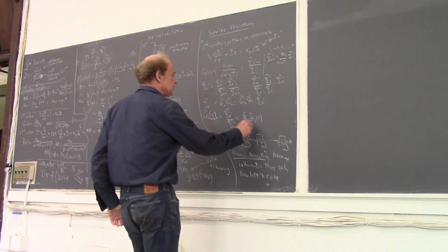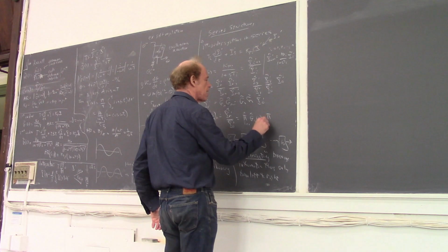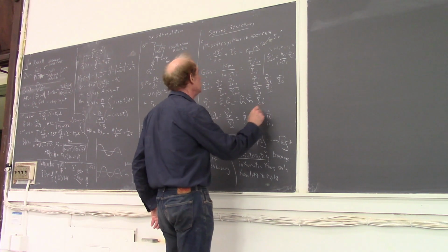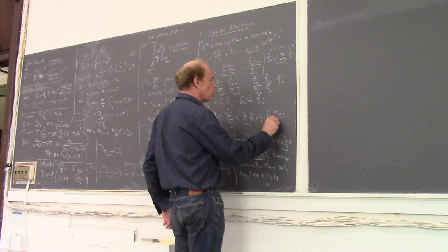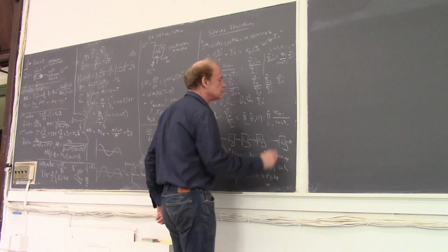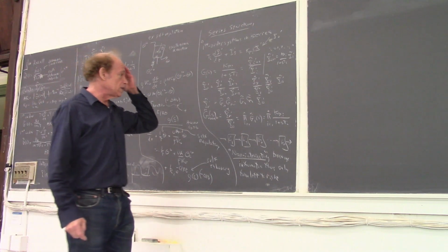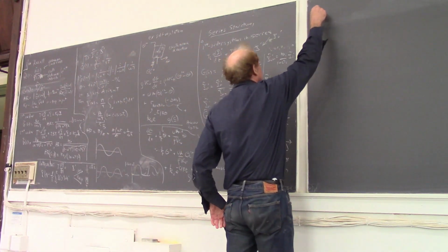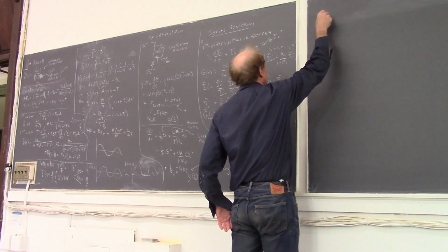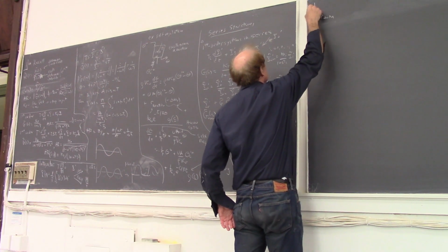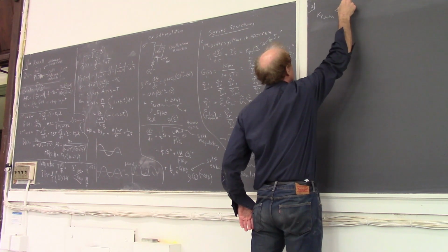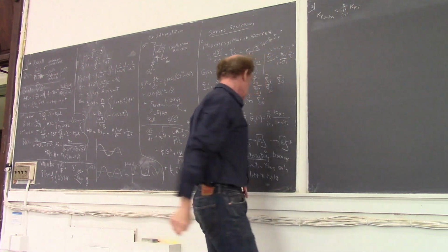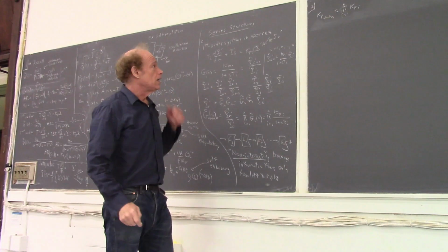And then we have something nice here. This just becomes the product, i equals 1 to n, of Kpi over 1 plus sτi. So what does that mean? That tells me that, for example, Kp total is just the product, i equals 1 to n, of Kpi. I'll just multiply the Kpi's out.